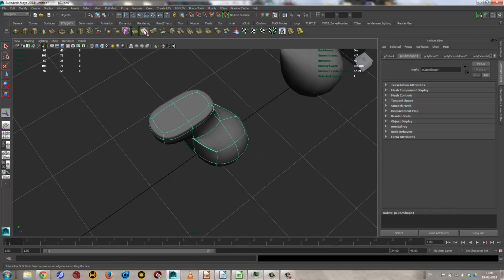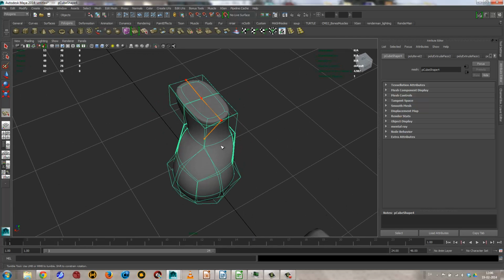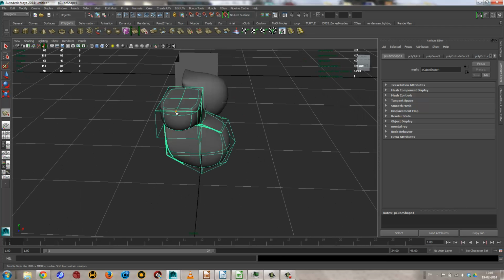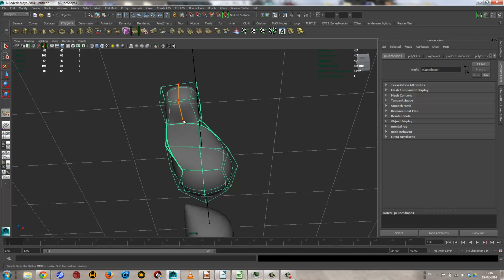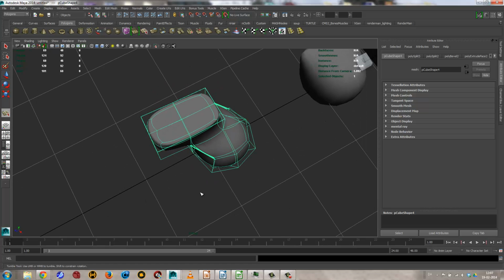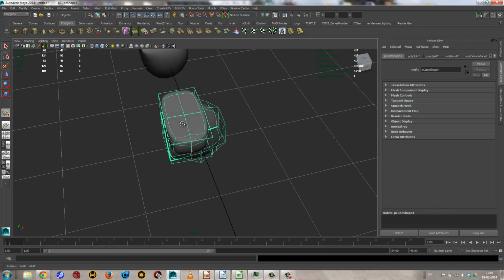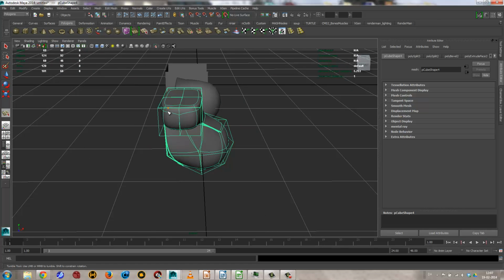And also the split polygon tool here, so I can go in and split polygons if I like. So I can split these like so. I'm just clicking. You can see it will try to find the right way, and then click, and then if I want to end it, I right click, and that applies the split to the polygon. There's a lot of different options in here.